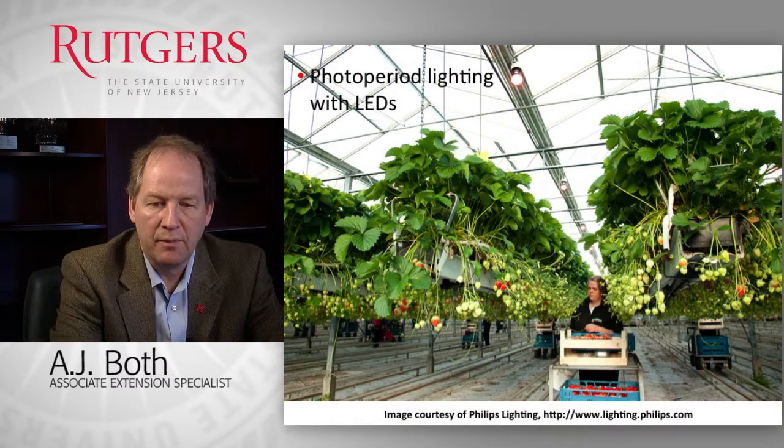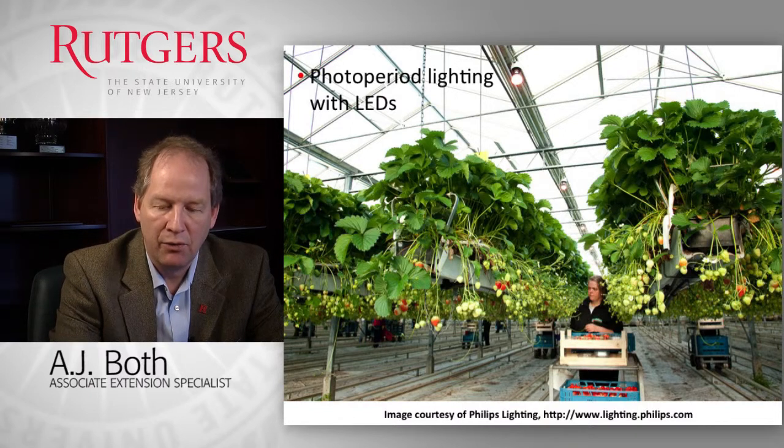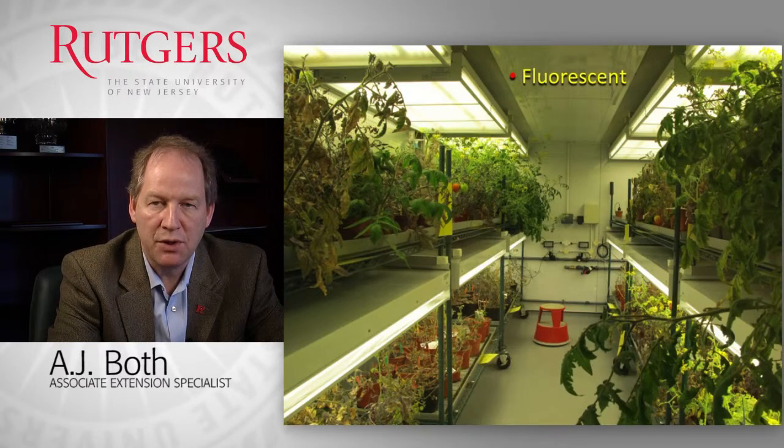Here you see LED lamps being used for the same purpose, for photoperiod lighting, for strawberry production, to make sure that the plants start flowering when needed and continue to flower for optimum berry production. An example of fluorescent lamps used in a growth chamber. Typically we use the tubes that, although not highly efficient, provide a very uniform distribution pattern that is very handy for small areas such as growth chambers and germination facilities.